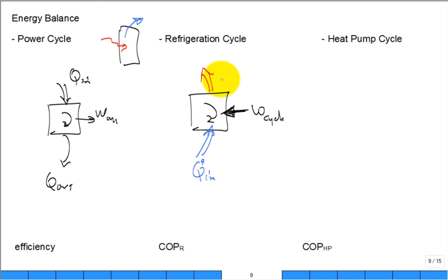No, hold it back away from the wall so it has a nice chimney effect back there and it'll work better. Or it gets all clogged up with cobwebs and other dust and lint, and you wonder how it transfers heat. What about the people that have a refrigerator in the garage? It has to dump heat to an even higher temperature in August, but it's a little easier in December because it's colder outside. So, yeah, really. But you have to dump this Q out.